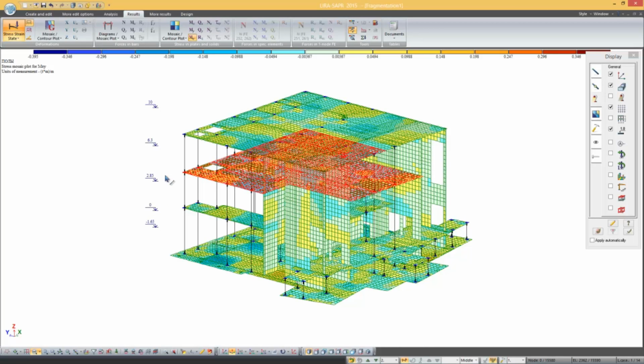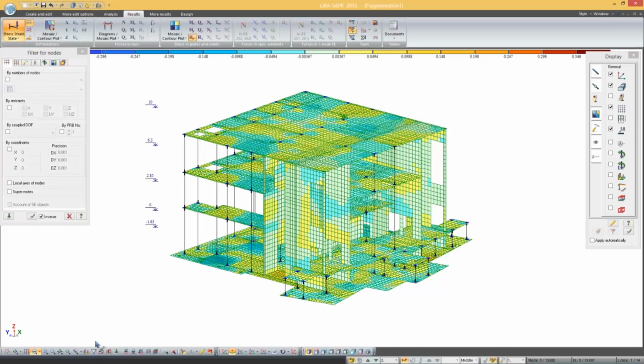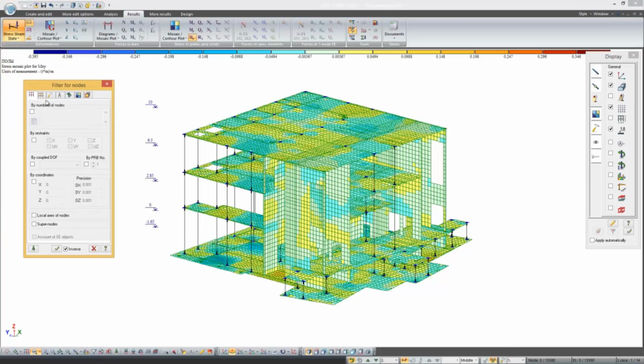There are also other tools for selecting elements and nodes of the design model. One of them is Polyfilter. Polyfilter works with properties of nodes and elements, geometry, and with orthogonal and arbitrary planes. In our case, we will use the last tab, section and cutoff.